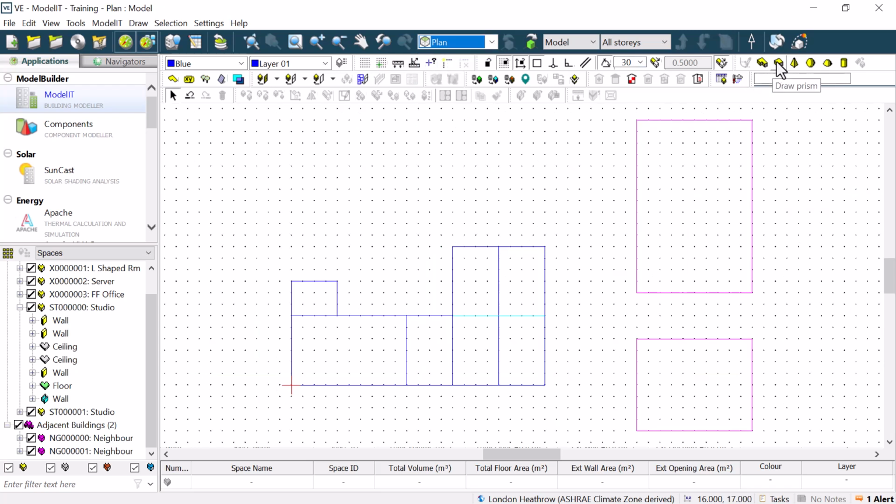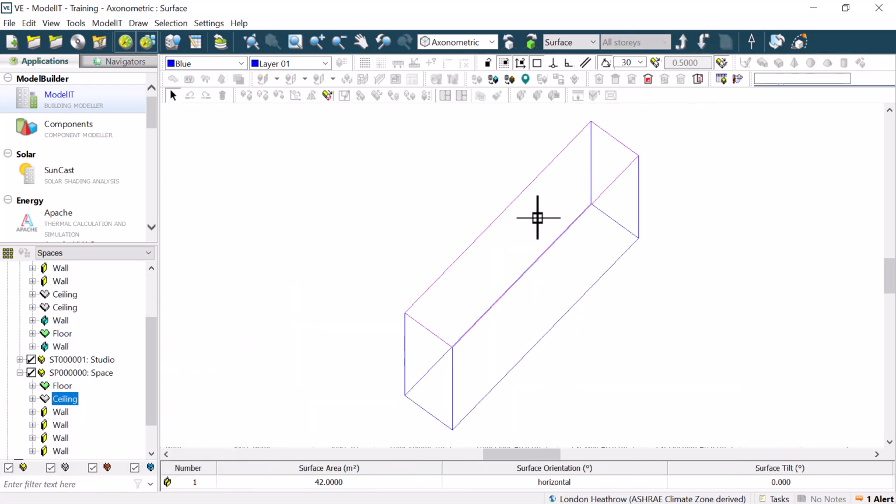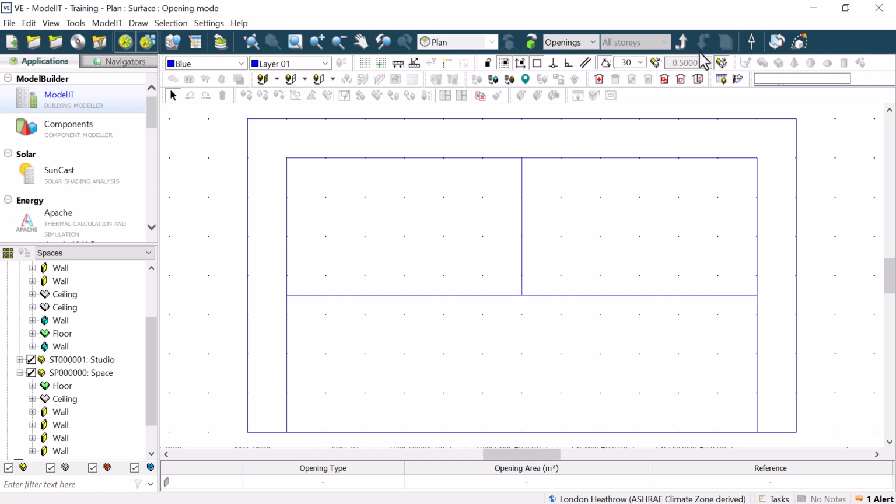We then return to Plan View and draw a single space flush against the elevation where we want to draw the windows. We make sure to draw this space as longer than or equal to the full length of the building, with the same base height and a total height that is higher than the height we just measured. Next, we go down a level into this space, and then down into the surface that is against our model. This effectively gives us the same view as the architect's drawing of the facade elevation.